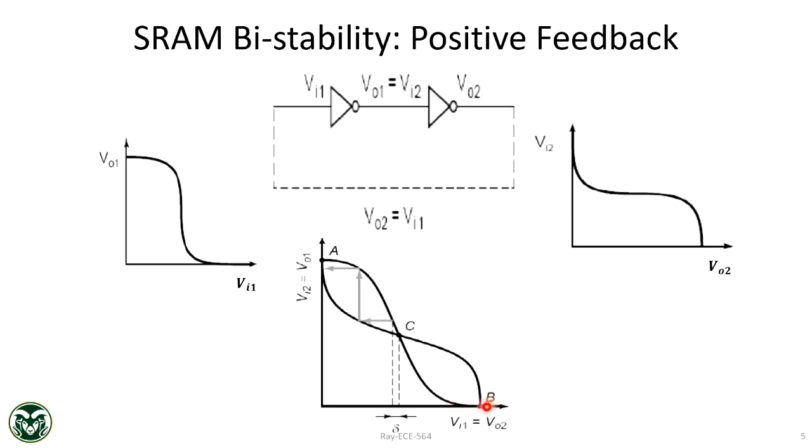Now, when you power it up, right, first time you turn it on, that time what happens? So that time, what are the Q and Q bar? When you turn on the transistor, right, what do you think? Will you be at A, will you be at B, or, yes? It depends on the process fabrication, which transistors are stronger. Yeah, that's the correct answer.